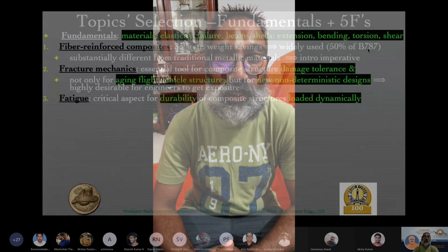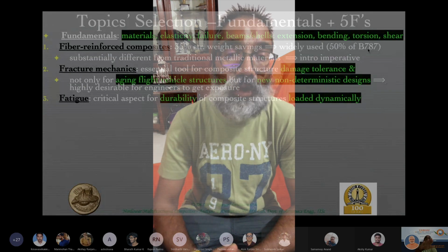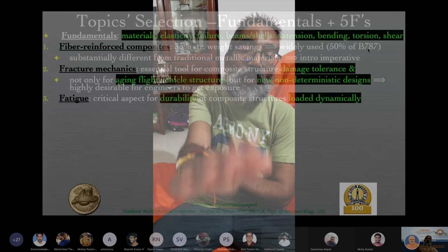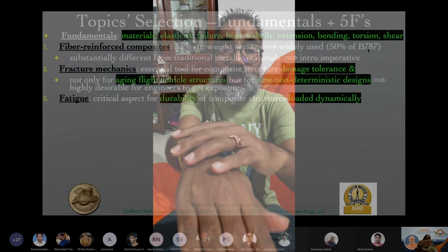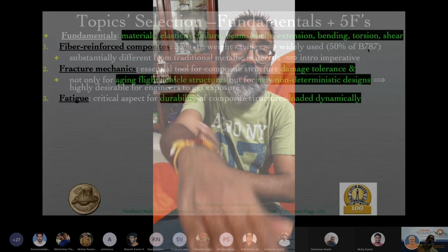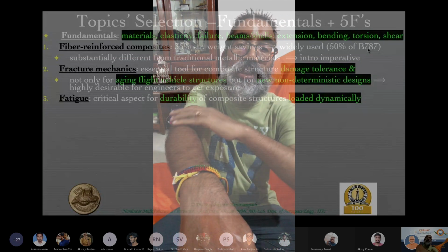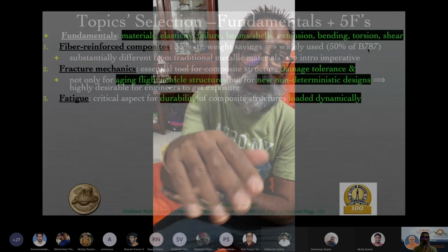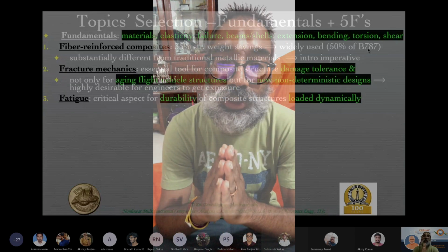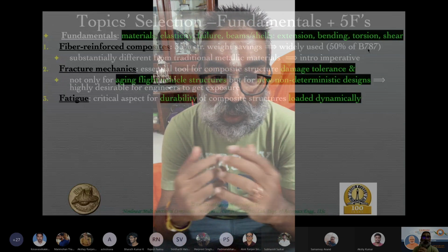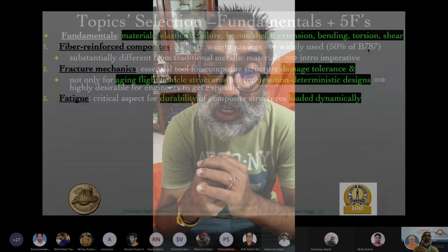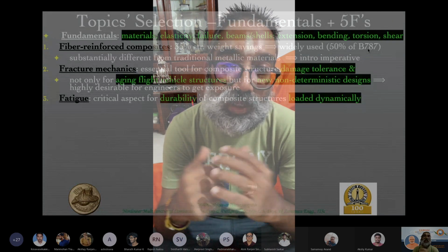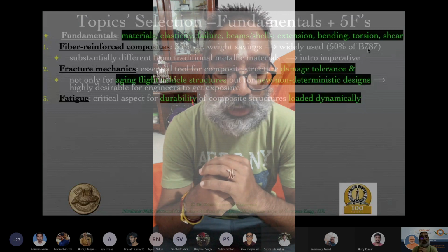We talked about a very classic example in the previous class where we saw that the aircraft wing, because it's undergoing a lift, therefore it's bending upwards. So the top skin, for example, undergoes compression, and then when it comes down and lands on the ground, it's basically the self weight, which means it's going through tension. So this is basically a low cycle fatigue, but there are many high cycle fatigues as well. In other words, higher frequency at which this can happen, because there are vibrations that are involved because of the loading that is there, coming not only from the air loads but the other loads that we will see shortly.